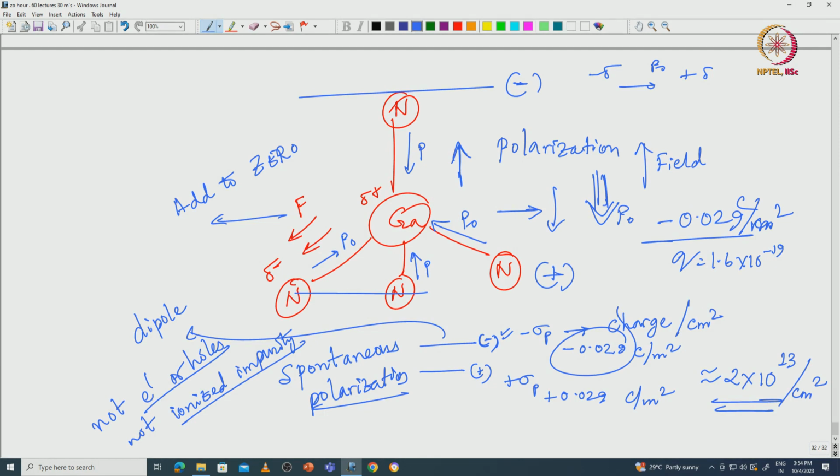So this is a very different, unique and interesting property of gallium nitride, that helps make gallium nitride transistors, HEMTs, without even using any doping. Now if I take one layer of gallium nitride, there is minus, there is plus. If I take another layer, there is minus, there is plus. So this plus and minus will cancel. Then I have another layer, minus, plus, and this minus and plus will cancel.